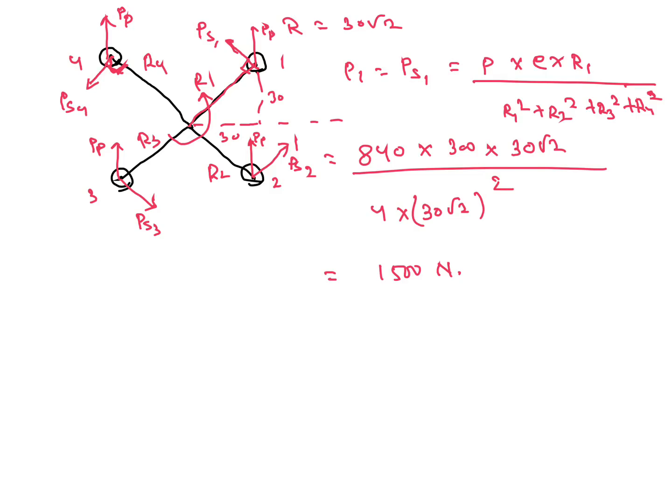So secondary shear load is opposite to that of eccentric load rotation. It's counterclockwise and perpendicular to this distance. So here heavily loaded are 2 and 1. You can take any one. The shear load on the worst loaded rivet, worst loaded is 1 or 2. So this is theta value.